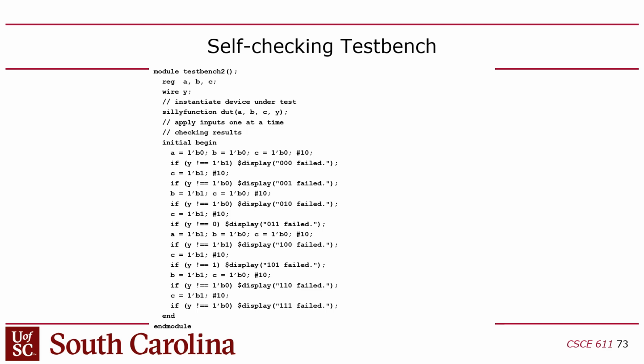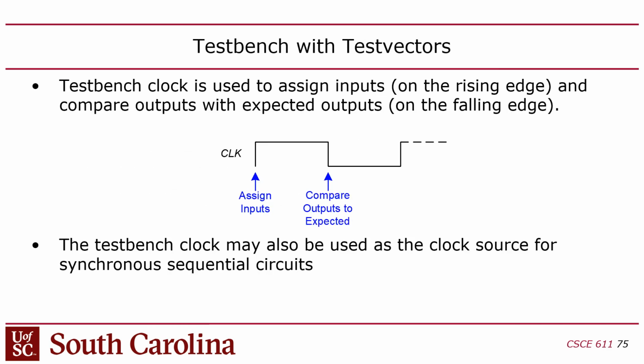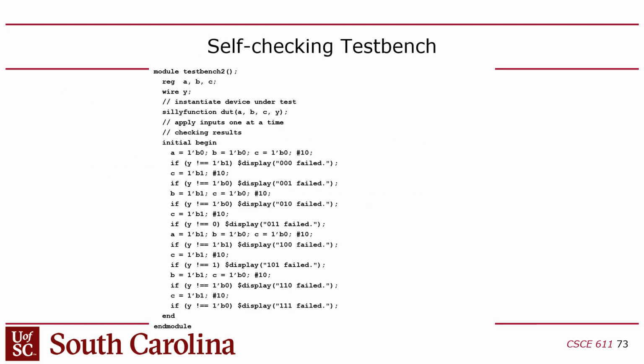So what's better is to write a test bench with test vectors. Now the problem with this is you have to figure out when you write a test bench how you're going to synchronize when you set the inputs, even on a combinational logic circuit. Now I mentioned to you guys, let me clarify something just to make sure I didn't confuse you with this.